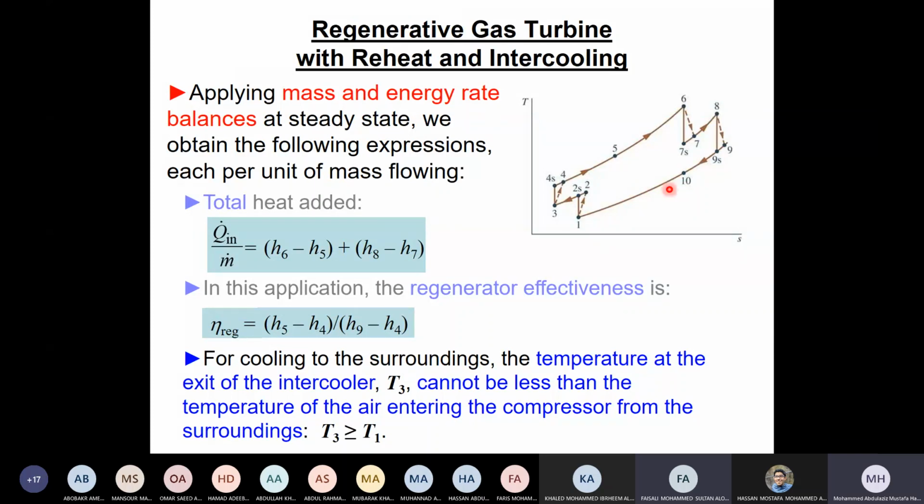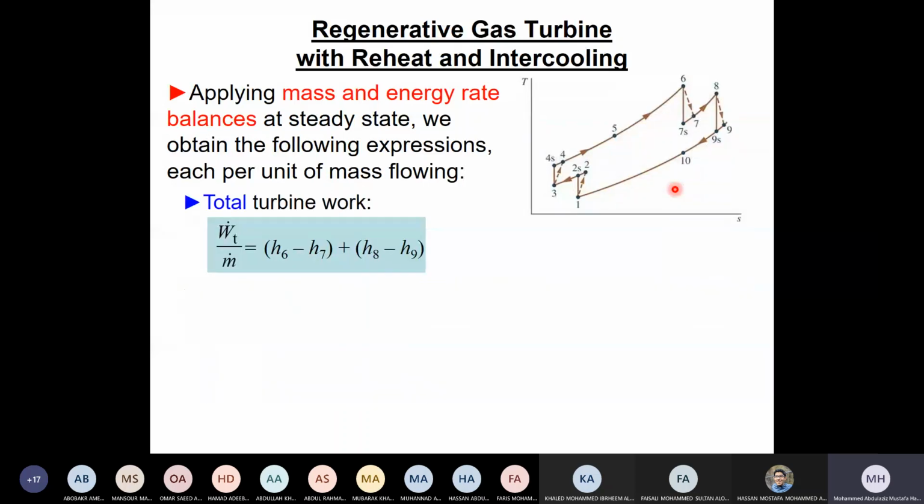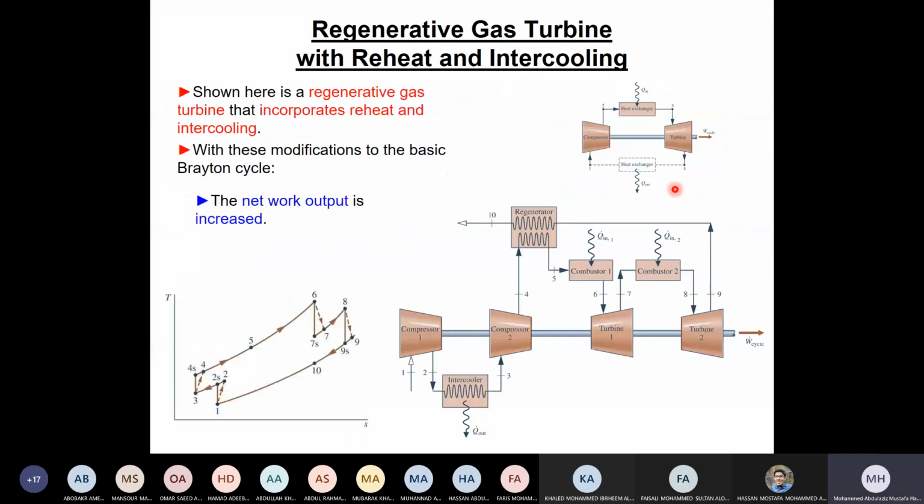Let us look at the diagram here. Where is the pressure change? Of course, in the compressors the pressure changes. Here we have pressure loss, but of course we neglect that. From 2 to 3, we say the pressure is constant. This is an approximation, and we are not going to consider pressure loss in thermodynamics. We leave it to another course. There is some pressure loss, but it can be neglected.